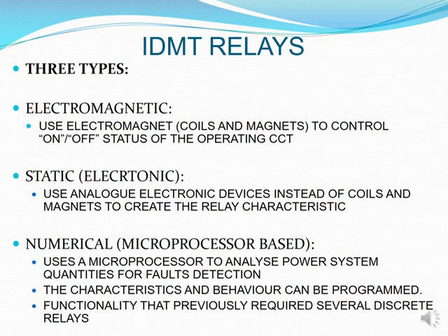Microprocessors are utilized in order to analyze what is happening in the system all the time. And once a fault is detected, then the behavior characteristics need to be programmed into these relays so that once it picks up this level of current in the system, it knows this is the function that it needs to do.